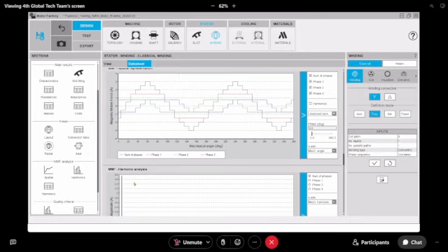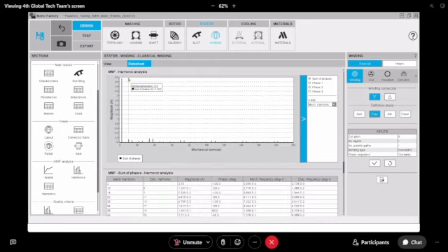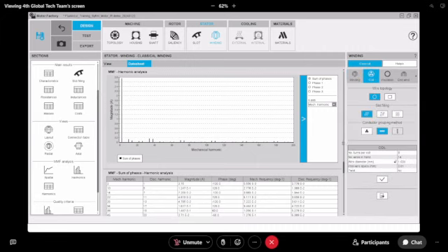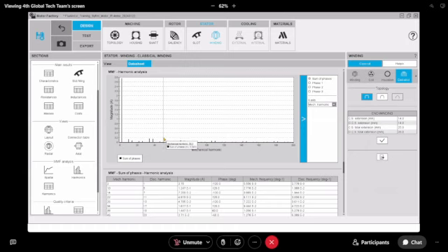Then this MMF should be sinusoidal and with a low number of harmonics. So depending on the possible configuration you select here, you have to look at the fundamental and the harmonic distortion, total harmonic distortion. Then the number of wires, the number of turns, end winding, and so on. And then the materials.